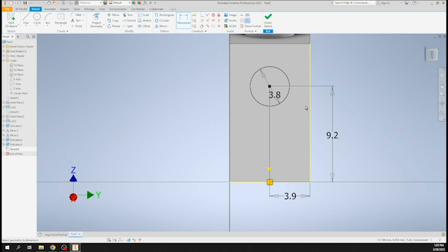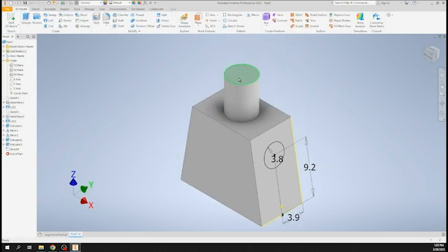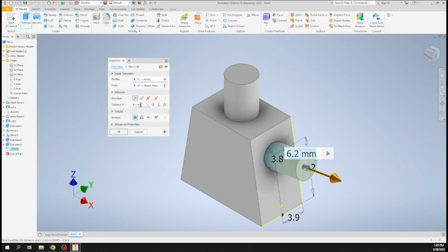All right. Now we're going to finish that sketch, and we're going to go ahead and extrude cut that. So make sure you're going the other direction and it's cut, and it's going to be a minor cut, only 2 millimeters, okay, just 2. And hit OK.